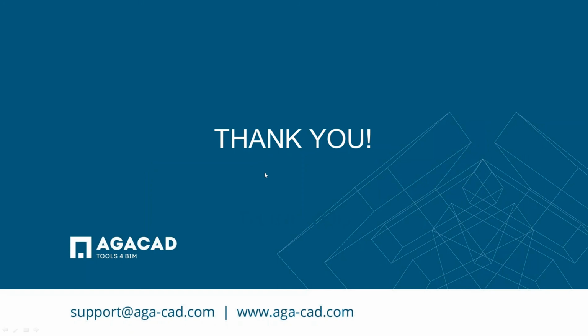Dezio is asking, if there are any changes in the model, we need to update some openings. How does Cut Opening manage those openings already inserted? Will they be deleted, moved, or not needed? So if you move some elements, like structural elements or any elements, you will get messages from Cut Opening, and you will be able to update those openings, and they will pop into the right places.